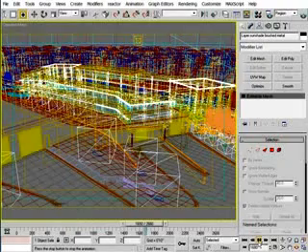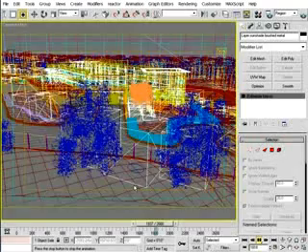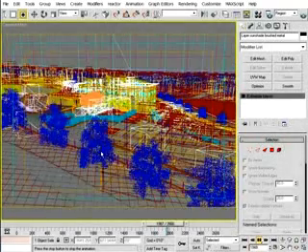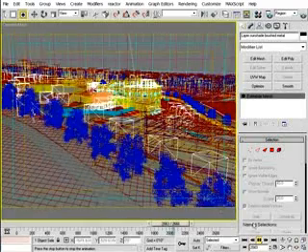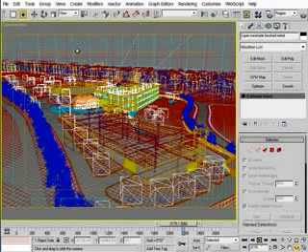In this scene, I have several buildings, some 3D terrain, a bunch of 2D trees in the background, and dozens of high-poly 3D trees in the form of VRay proxies. I kept this rendered image size fairly small to make the rendering finish quicker, but the point is, when I render the scene using the static geometry option with 600 megabytes of dynamic memory, my rendering time is 3 minutes and 59 seconds. Now if I decrease the dynamic memory limit to 400 megabytes, which is the default value, when I render again, you can see my rendering time is basically the same.